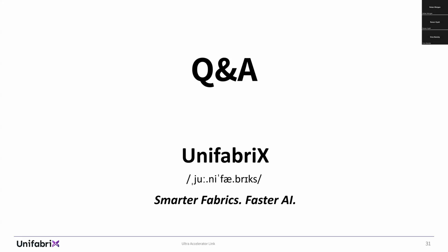Next question, is a UALink port limited to 4 physical links? Currently, UALink defines a station that could have 4 lanes, 4 by 200. The port could be 4 of these lanes, could be 2, or could be 1. Future revisions of the spec may define other types of ports. Today, it's by 4.